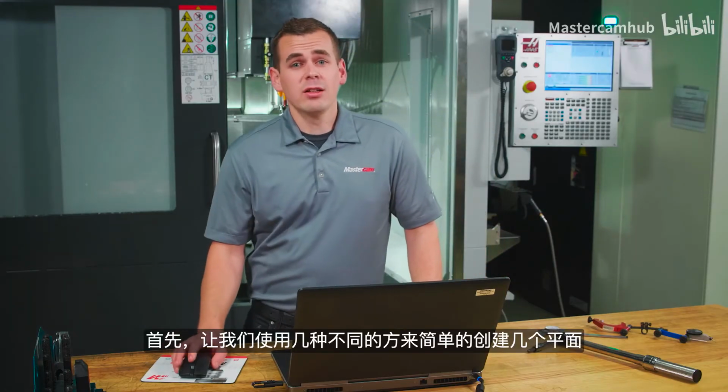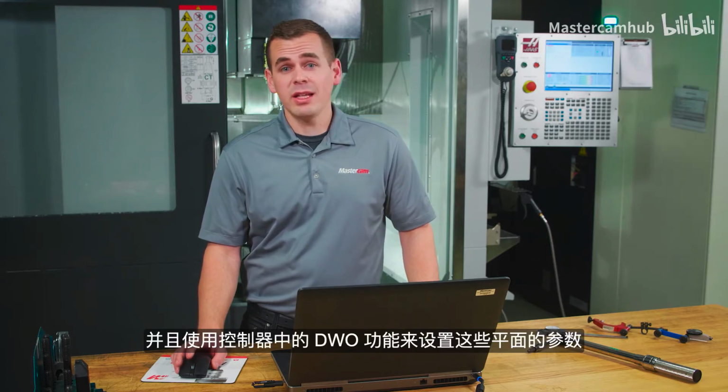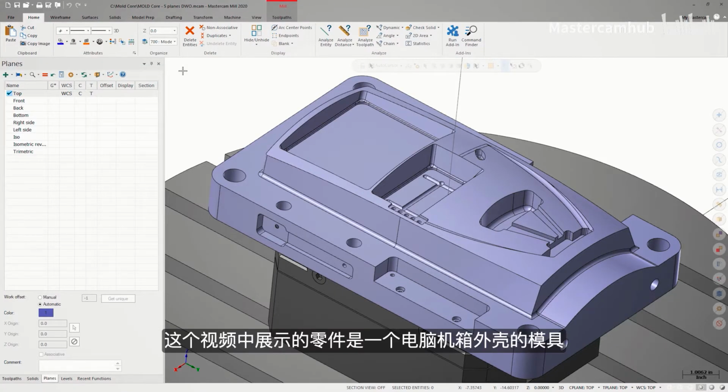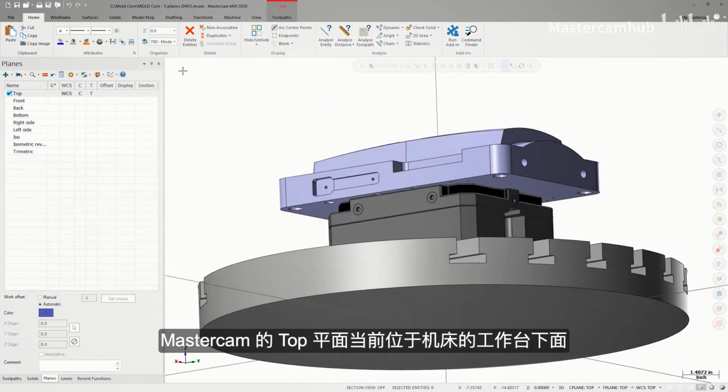Let's start out by taking a look at a couple different ways to easily create planes and how those planes relate to using DWO on your control. The part we'll be using for this demo is a mold for a computer tower. The Mastercam top plane is currently located below the machine's table.